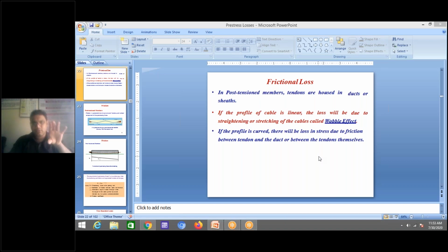Let us take a beam with its centroidal axis. If your strand is placed at the center of the section itself, the force will be axial only. Now take a rectangular section where your strand is not at the center but below it, with some eccentricity from the centroid of the section. That is called eccentric stressing. Axial stressing is the stressing applied through the center of gravity of the whole section. Eccentric stressing means there is some eccentric distance from the center of the section to the point where the force is applied. Okay, Mohan. Clear, sir. Anything else? That's it.